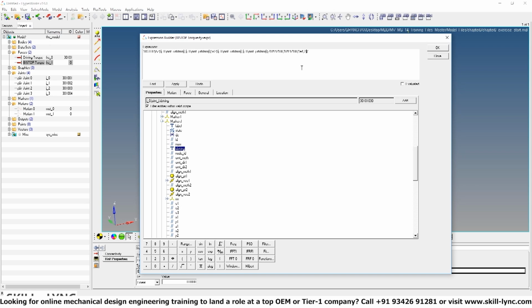After entering the deformation characteristic, the last thing is to enter the damping. 100 is the maximum damping coefficient, and the last thing that we'll have to enter is the penetration. So that's 0.1. You see this expression is too huge. It's very easy to make mistakes here, but if you do it carefully, then we can enter the expression without any mistakes.